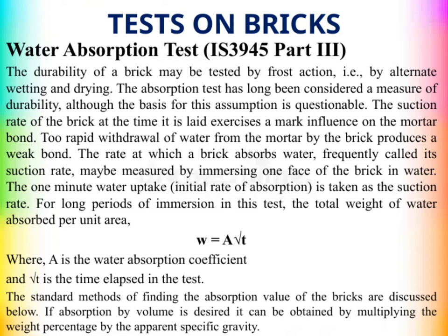In this slide, we're looking at the water absorption test, which is outlined in IS 3945 Part III. This test helps us assess the durability of bricks, particularly through their resistance to frost action, which involves cycles of wetting and drying. Now, while this absorption test has traditionally been considered a good measure of durability, it's important to recognize that the scientific basis for this assumption isn't entirely solid.